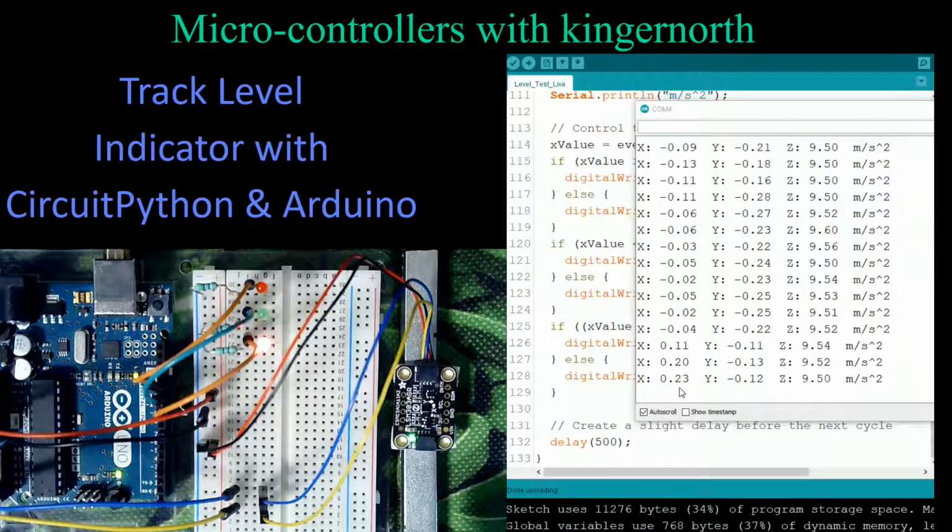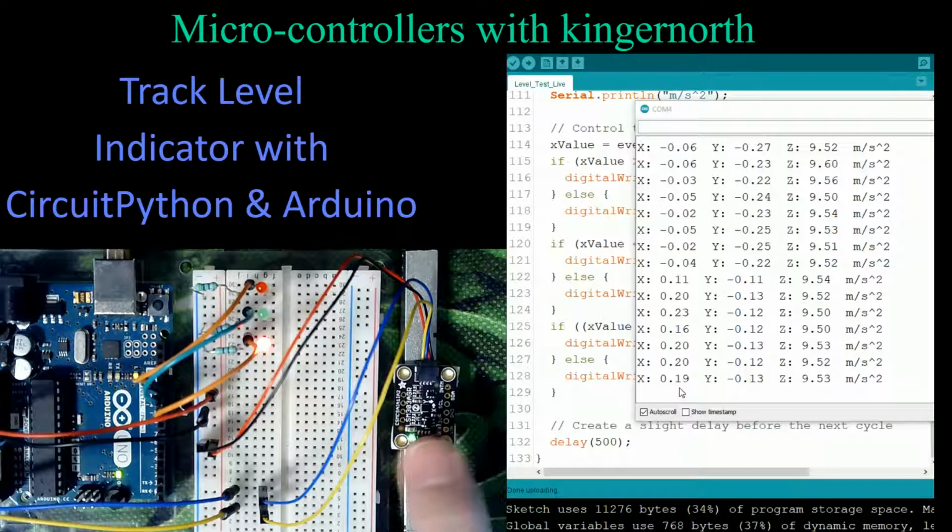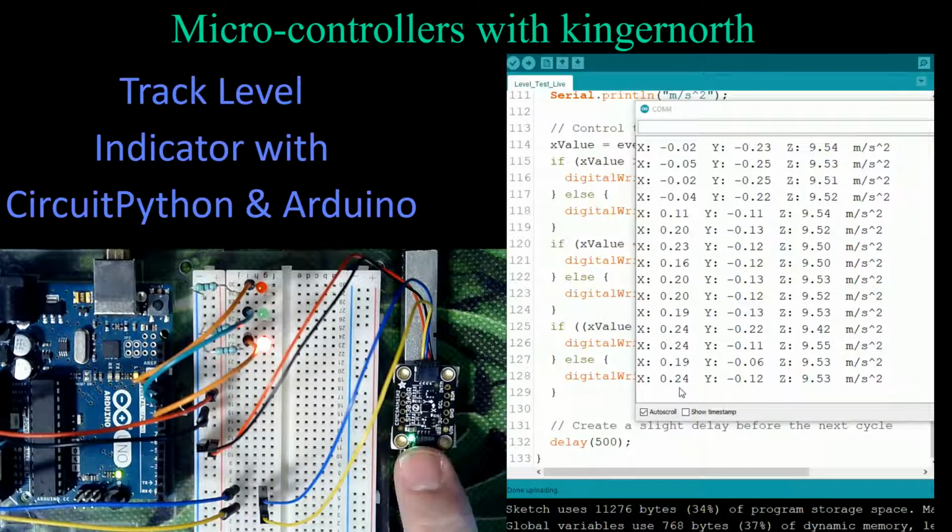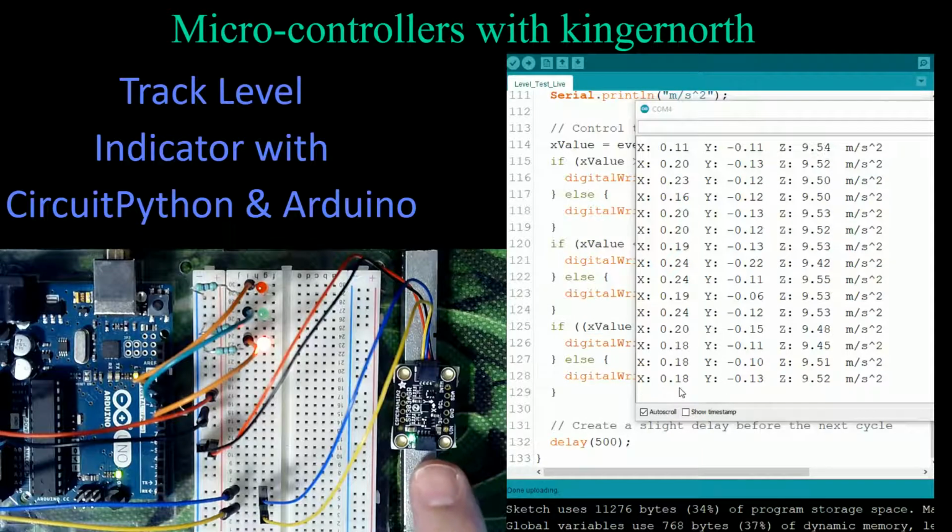Now I talked about calibration. There's a couple things you can do for calibrating. When you're mounting this, make this board adjustable, like a hinge where you can rise and lower it. Maybe use shims on one side. Shim it up on one side when you screw it down to your block. It's got 4 mounting holes on it, which is really handy. And then when you're screwing it down, put little shims in here until the board sits level on a known surface. And once you've done that, you're done.